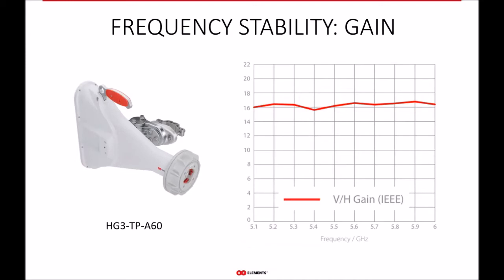I can guarantee you will not perceive this difference in the slightest. So in that sense, the frequency stability of the maximum gain is really high. There are actually two curves in this graph, one for the vertical and the other for the horizontal polarization. But because they're overlapping, you can't see the difference, which again is another good property of horns.